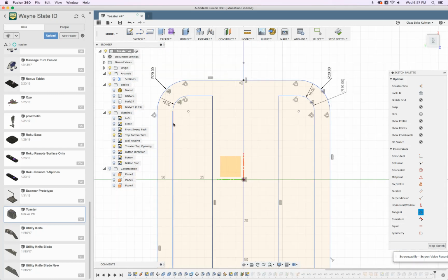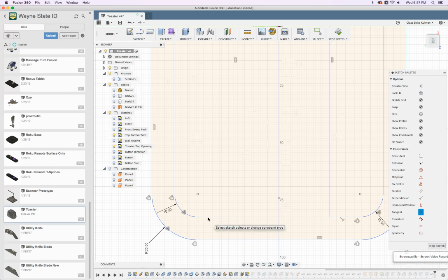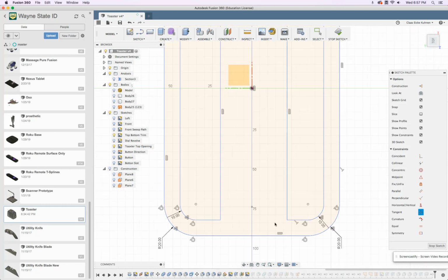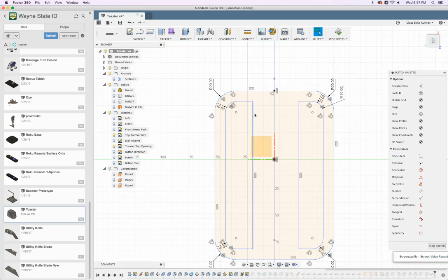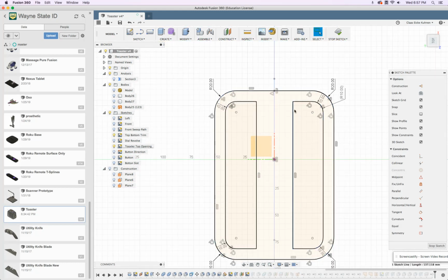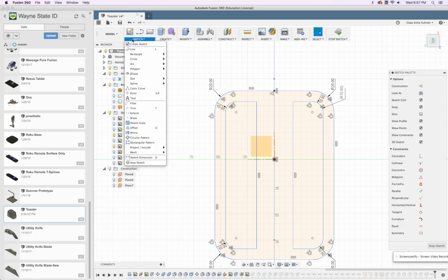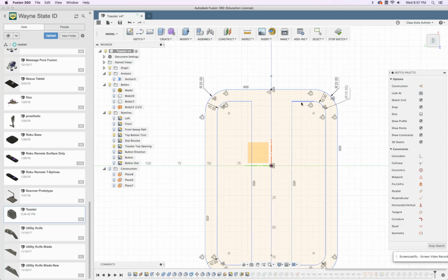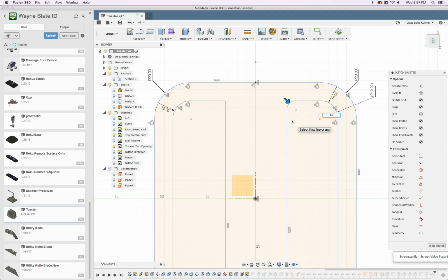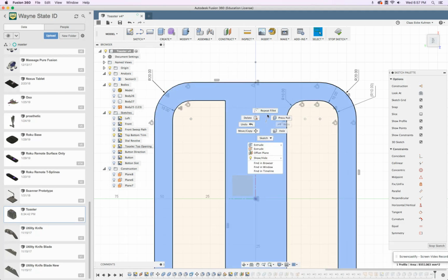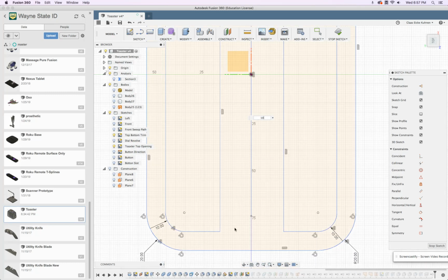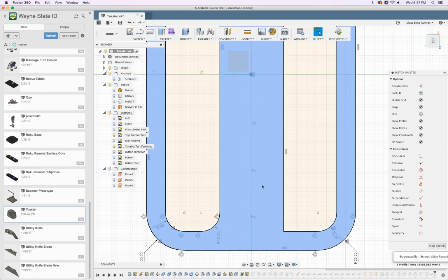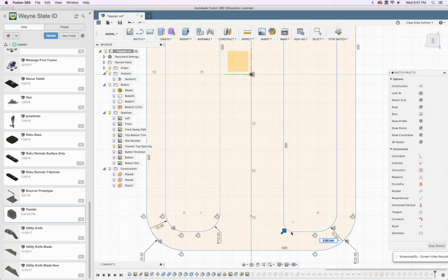So there. I'm going to make all these lines correct. Here, delete this one. So now bring this over and there. These corners now we have to all fillet. Sorry, not trim. Fillet it with a radius of 10. There. Right click. 10. Right click. 10. Right click. 10.